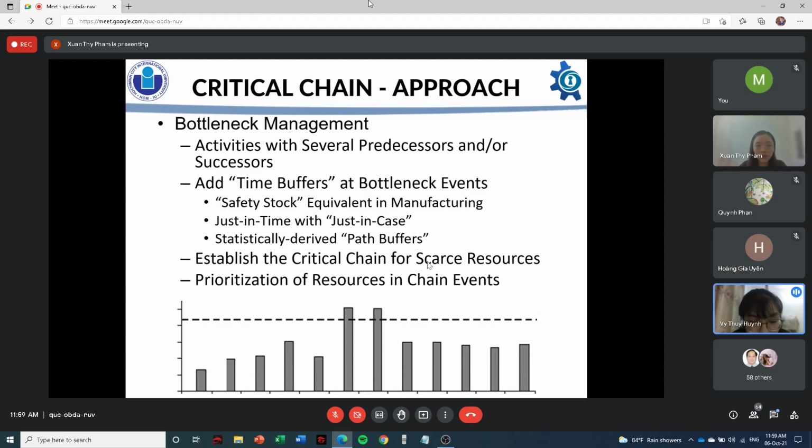The first step, identify the constraints of the process or the system. It is important to identify the bottleneck. If the bottleneck is a machine, maximum utilization must be achieved to ensure there's work to do for this particular machine. Second, determine how to exploit the constraint. We must find every way to ensure the bottleneck is fully used. This could mean reducing the number of changeovers, offloading work that can be done on another machine, or reducing setup time to create additional capacity.